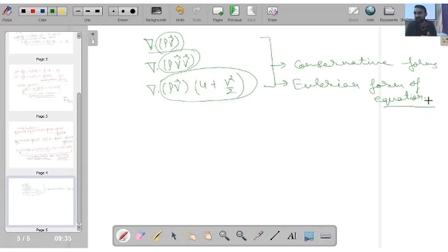So whatever our momentum equation is, that is called Euler's equation. That comes from the name of the scientist, and this Eulerian form of equation comes from the physical understanding that if our control volume is fixed in space and we have flow across the control volume, and in that control volume we are studying the variation because of the spatial parameters and the time parameter, then we call it the Eulerian form.